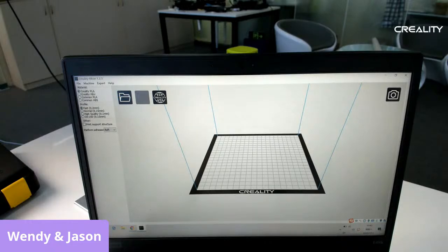So it has Creality PLA, Creality ABS, and if you're using a different brand, it's the same thing, PLA, ABS. The second option would be the speed of the print. It says fast, normal, high quality, or CR10. There are four options.